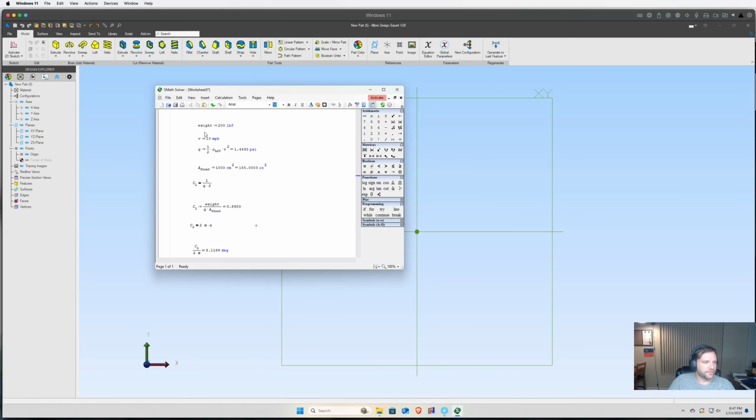So we have their weight is equal to 200-pound force. We have the area of the front, which is equal to that. And this is where we have to make another approximation and say, well, the span of the front wing is going to be 1 meter. Just as an approximation. That's roughly the size of foils out there. Usually they're a little bit more narrow than that, but I think that's mainly for shipping, packing, and travel constraints. A lot of the boards, in fact, the Formula boards were limited to, I believe, 100 millimeters or a meter, just for shipping reasons.